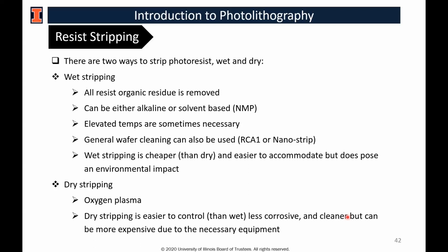However, traditional photolithography resolution is actually dependent on the diffraction limit of the UV light you use. The UV wavelength is 365 nanometers. Sometimes for deep UV, it's about 200 nanometers. If you want to achieve sub 100 nanometer features, it may not be possible using traditional lithography. So we need to turn to a new lithography method, which is the e-beam lithography.